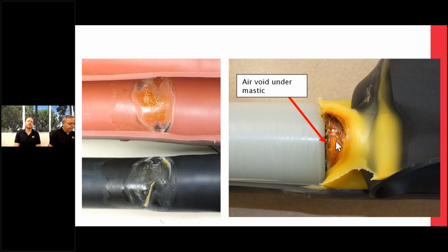Now, the problem here was this lug should be, I don't know, 5 millimeters to the right, where you allow a bigger gap for the yellow heat shrink to go into that gap, for the mastic to go in, so that you get rid of the gap and get rid of all the sharp points. But because the gap was too small, the yellow mastic couldn't go in, and that was causing sparks to jump across this gap. The sparks were creating heat, and that was heating up these heat shrinks, the red and the black heat shrink, which you can see on the left-hand side here.